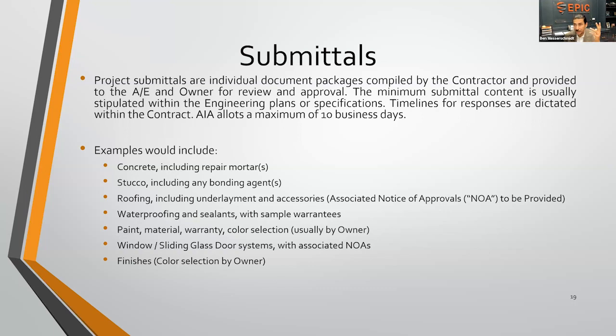The more, the better. You likely want to also see, let's say, a color sample. If you're going to talk about finishes, it's going to be very crucial to get the approval, from a material performance standpoint, from your architect or engineer, and then an actual color selection by the owner.